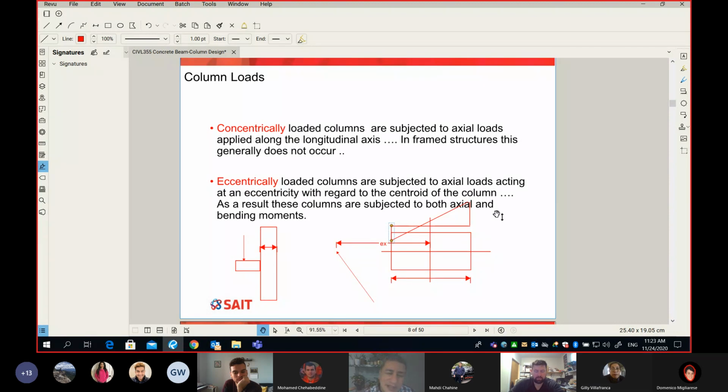Okay, I bet you that he said that when you think about a foundation or footing where the force is not in the middle, or maybe a foundation that has a moment on top of it, it causes one side to be in a higher stress and the other side will be in less stress. What we don't want to see is tension on one side. And that's why the force has to be within the middle third of the section, which means I'm going to dimension it on my section.